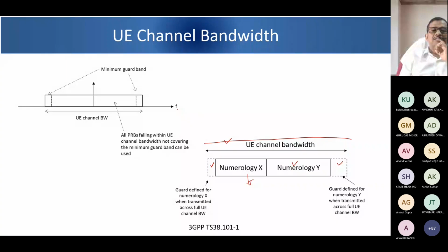Similarly, the locations of those subcarriers or PRBs are fixed in the standard. What I mean is that you cannot just start your subcarrier from any point. Those points are already defined. So in case the channel bandwidth is given to you by DOT, you have to look at the specification and first leave the guard band.